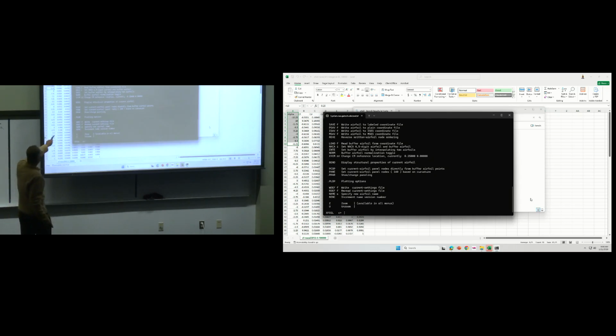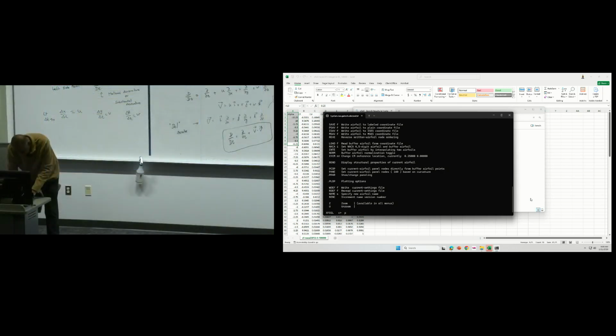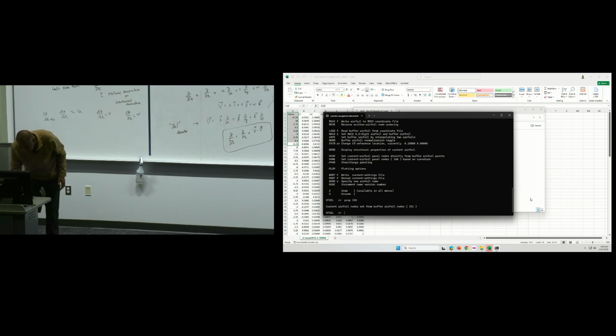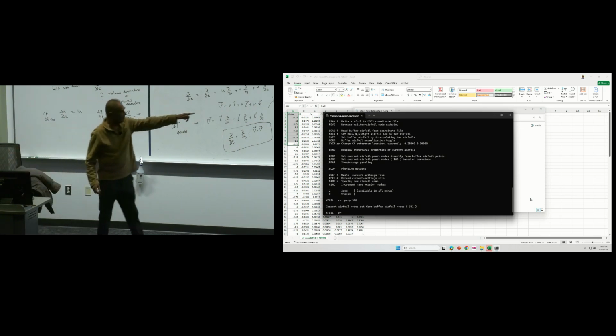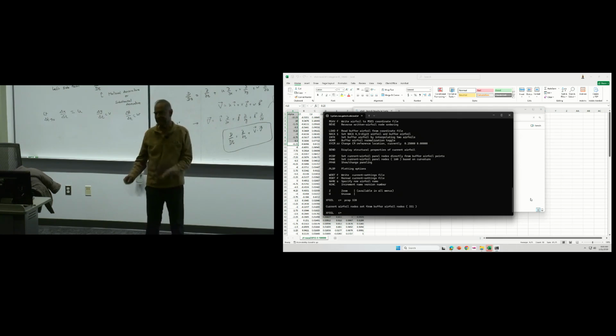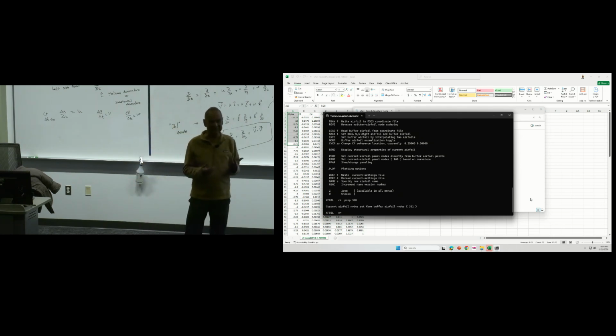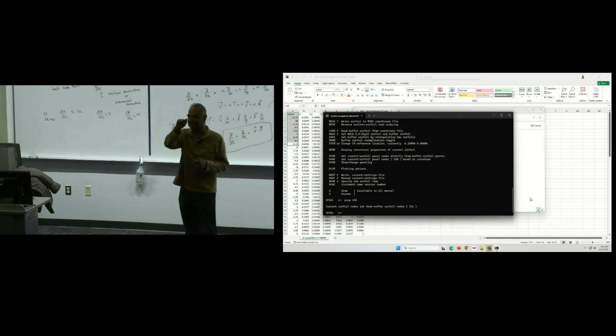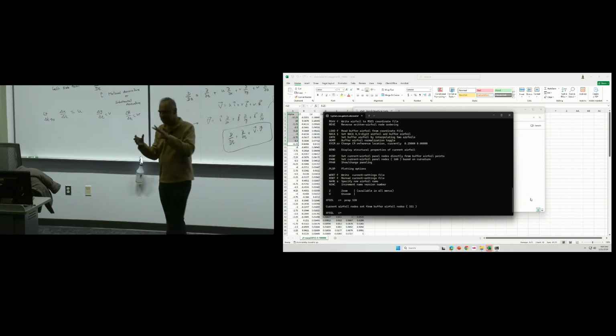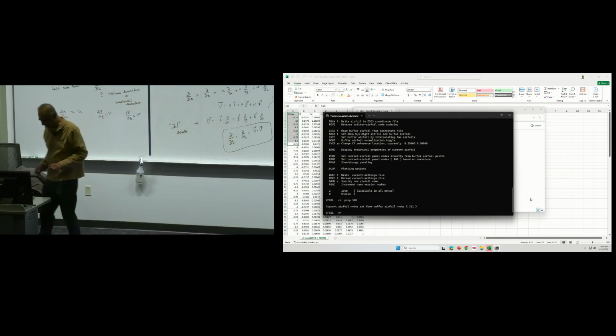Or you could also use another command called PCOP. You have to kind of play with it or read the manual on it. I have done neither, but let's see what happens. PCOP. And I'm going to put some number, 320 or something like that. I want to do the PCOP. Now I have double the points, 331 points on the airfoil. So what I recommend is you increase the number of points on the airfoil so that a ragged, jagged airfoil becomes a smooth airfoil in the eyes of XFOIL.